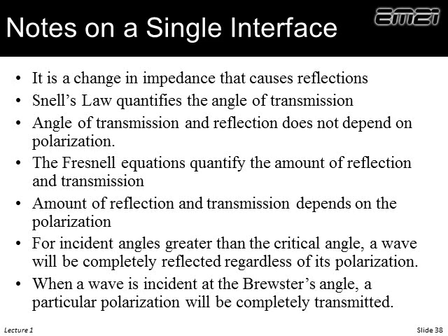So some final notes on reflection at a single interface. It is fundamentally a change in impedance that causes reflections. I could choose two different materials that have different dielectric constants and there won't be any reflections. I can choose two things that have the same dielectric constant and there will be reflections, because the dielectric constant is not the only thing that determines impedance.